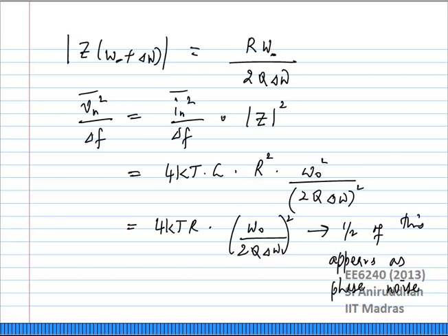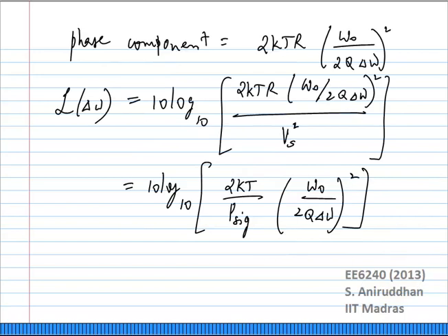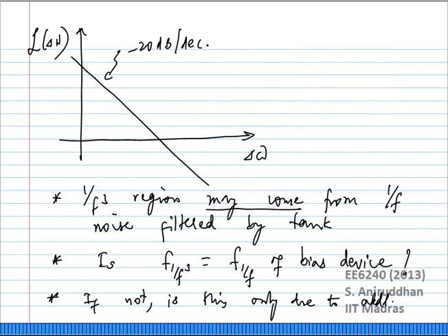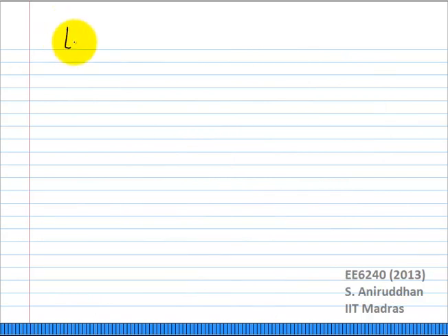That is the really important point you need to take away from here, as far as noise is concerned. We have come up with some kind of expression. Now we need to move from this LTI expression to Leeson's model. Leeson's model really is just this kind of LTI expression, but tagging on a couple of empirical factors to compensate for the 1 over f cubed region. So let us just write out Leeson's expression.